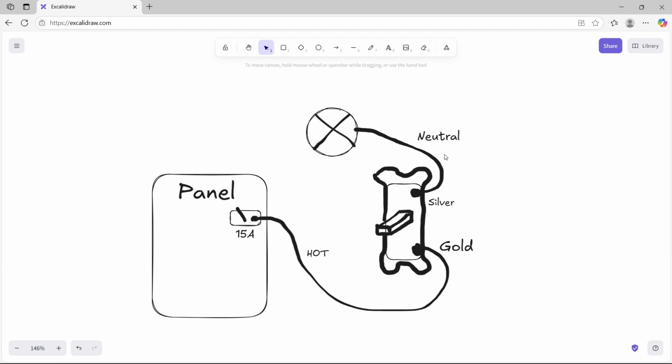If your circuit is not grounded at any point, the neutral likely still has a voltage across it, which means that it can shock you. But generally, the neutral and the grounds are going to be tied together at the panel, especially whenever you get to a transformer or any kind of high voltage switch yard.